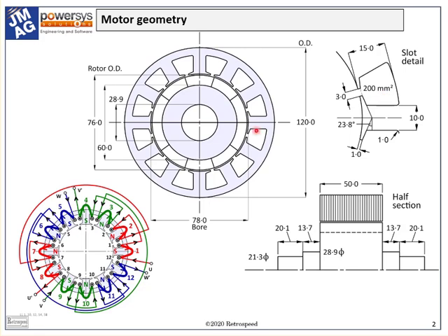We can also go back and have a look at the winding. You may remember we synthesized this 3-phase winding, and in that process we also calculated the winding factor at the working harmonic, 0.933. We will need the winding factor again in this section. In this winding, the number of coils is equal to the number of slots. So we have 2 coil sides per slot. Each coil is wound around 1 tooth, giving a coil span of 1 slot pitch.